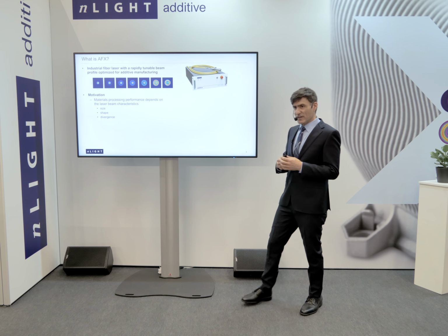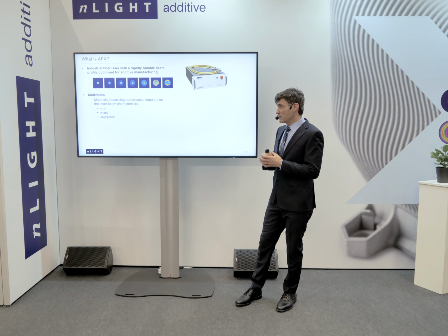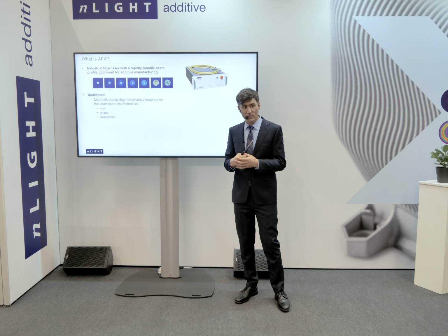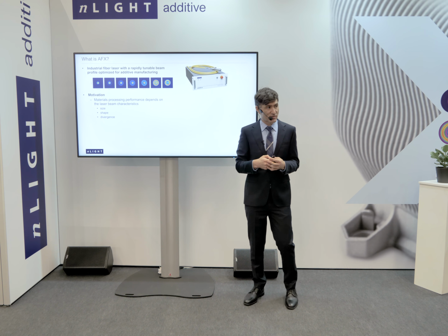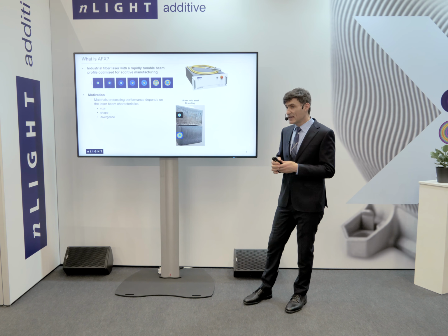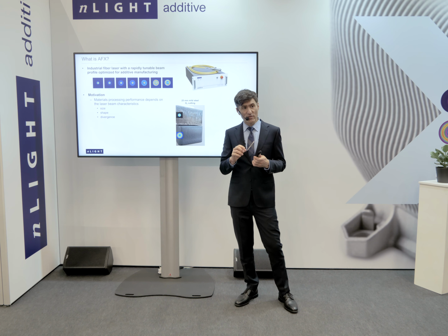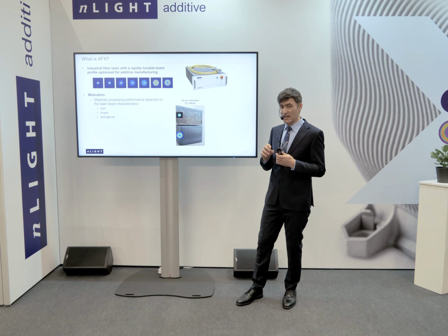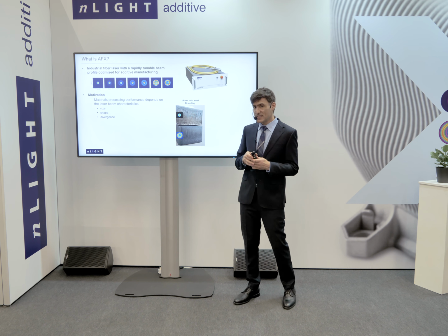The motivation for developing such a technology actually goes beyond additive manufacturing. In general, it's been known for decades that materials processing performance depends on the laser beam characteristics, the beam's size, shape, and divergence. To take two examples from more established or legacy applications, in sheet metal cutting, it's known that fiber lasers have really taken over for thin metal and nitrogen cutting, but for thick metal, oxygen cutting, particularly mild steel, they were not able to achieve the edge quality of CO2 lasers.